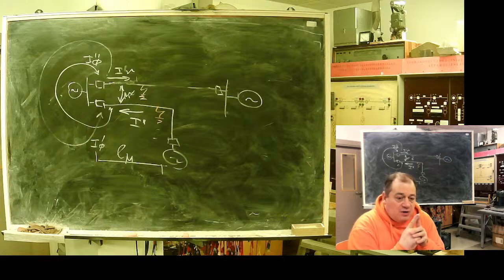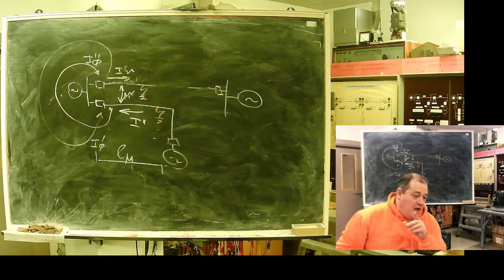On modern relays, it's better to use a separate fast zone activated for a short time. It's active when the switch is disconnected, and it remains active for 1 second after the switch is connected. It's a best practice for switch on fault. And now